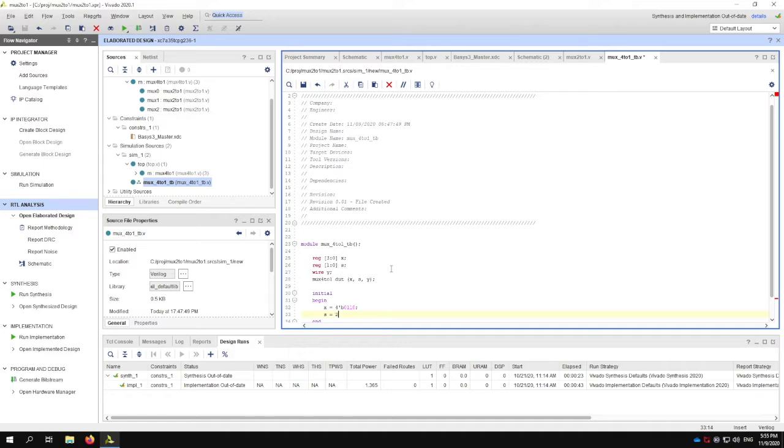S is 2 bits wide, and I'm going to give it the binary value 0, 0. So I would expect my output Y, recall that when S is 0, my output is going to be the 0th or least significant bit of X, which in this case is this guy, which is 0. So I'm going to observe the output in my waveform window once I conduct this simulation and make sure that this is in fact the case.